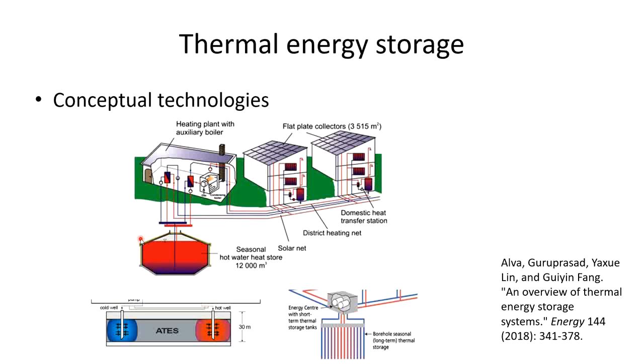So in this slide you can see different options of seasonal thermal energy storage, where one option is large water tanks built typically under neighborhoods of several houses. Some things like this can be seen as pilot applications, for example in Denmark or perhaps Switzerland. And this heat is typically not at very high temperature, so it is used mainly to partly heat up the return water before it goes to the boiler or before it goes to the heat pump.